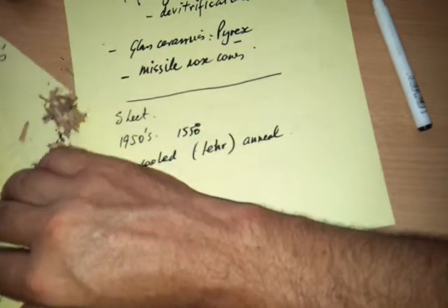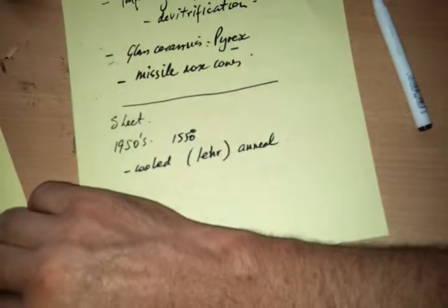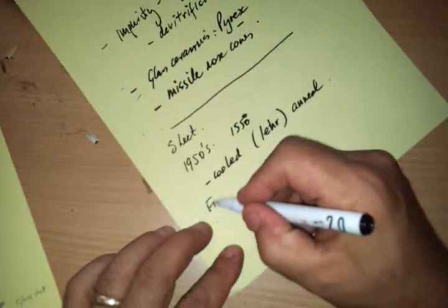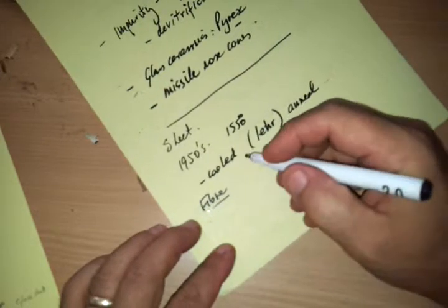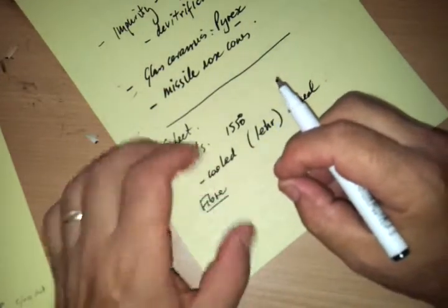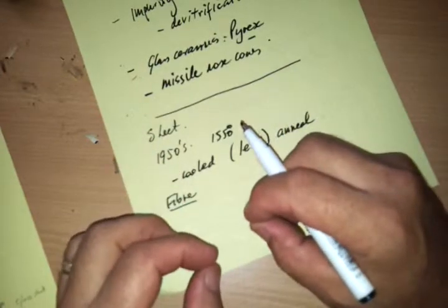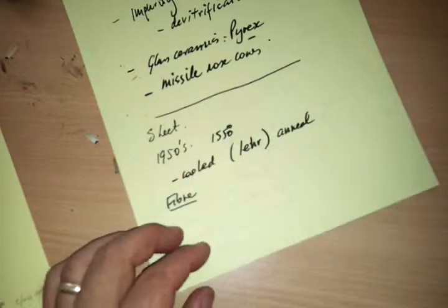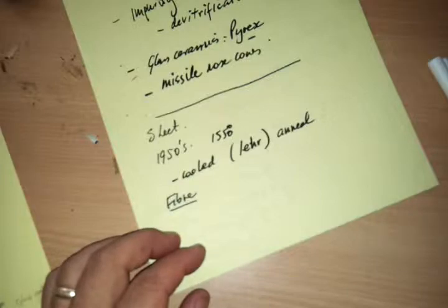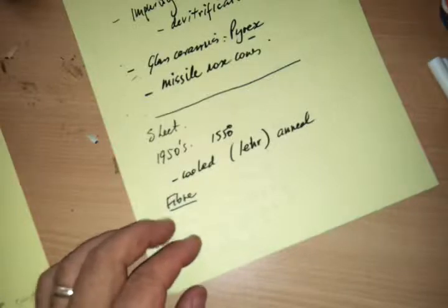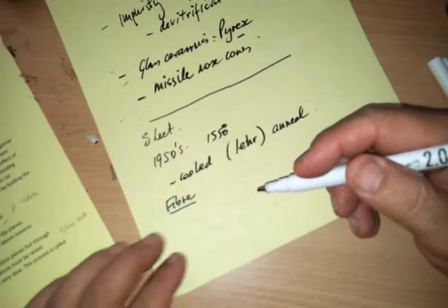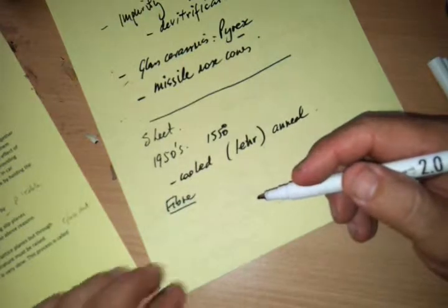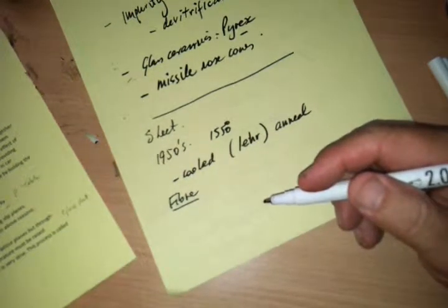Right. Now, glass fibre, on the other hand, which is used quite a lot as a reinforcing material, is created a little bit differently. Glass fibre can be up to 100 times stronger than a glass sheet. The main reason for that is because it has a very small surface area, and as a result there are fewer imperfections in the surface, which gives it very high, good tensile properties. So that's glass fibres. And how are they formed? Well, there are usually two most common ways to form glass fibres.